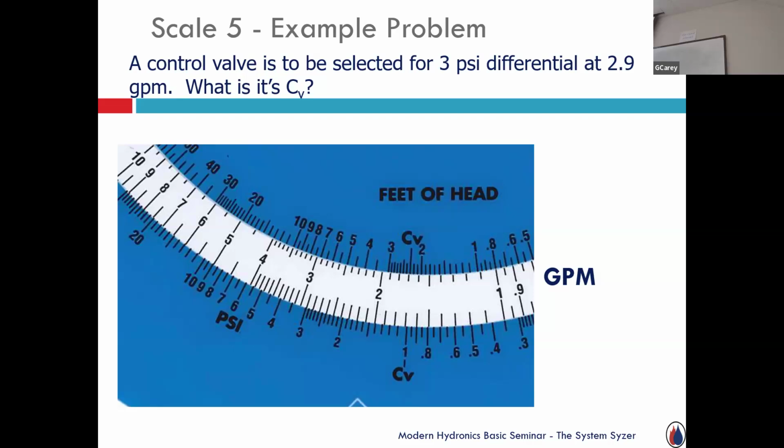It's a change in the water temperature. I'll take some return water, blend with the hot boiler, and I'm not creating this huge pressure drop, because usually on the other side of that valve is my distribution pump. And I don't want to create a huge pressure drop on the suction of a pump. So it's not like one size fits all. It's just what's the application where you really want to get critical.